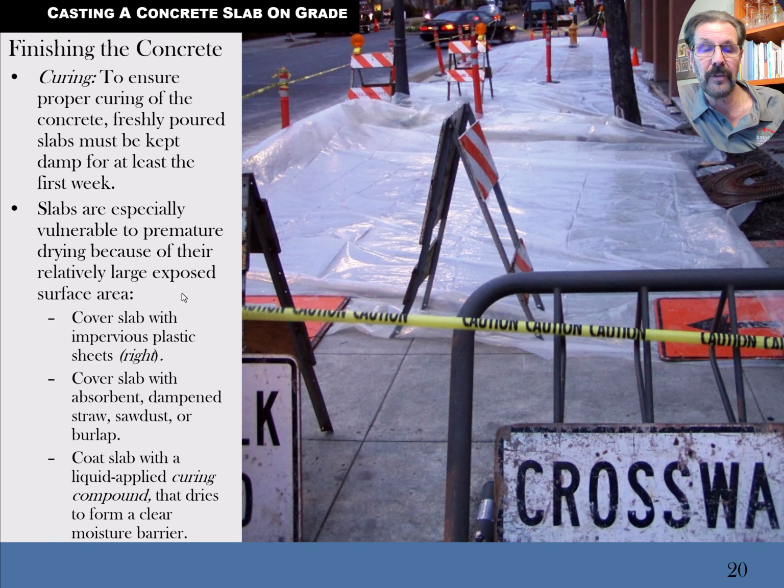Okay, let's see about finishing in the wintertime. We've got to do moist curing. In the summertime, we want moist curing. In wintertime, we want to keep the concrete from freezing if you're in an environment where that's a problem. In Louisiana, there's not too many days a year where you have to worry about the concrete freezing. That comes up every now and then, but it's not a common issue. A lot of times you see the weather coming, you don't even bother pouring concrete in it. You wait a few days and things change. That's the way it is in Louisiana.